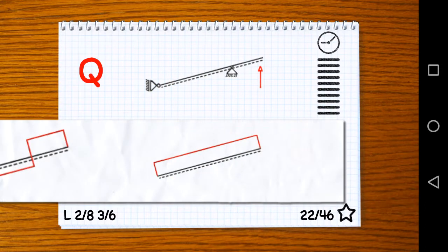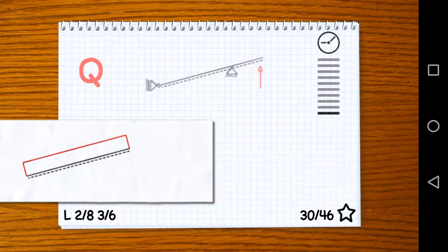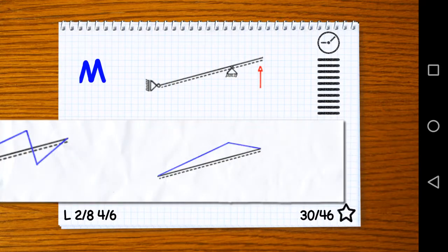Yeah, shear forces is what we're looking for here. We're just going to read the beam from the right to the left, and at the right end we have a single load already going upward. So what do we do? A jump upward. So it could actually be this right answer. It's not going to be though, because we still need to go back downwards because of the reaction force at the pin support. But this one, just about that information on the right side, could have been a right answer. The right one will probably be this one in the middle. So we're going to have a jump upward, then constant because there's no distributed load, then jump back at the pin support, constant, and back up at the roller support that was completely on the left.